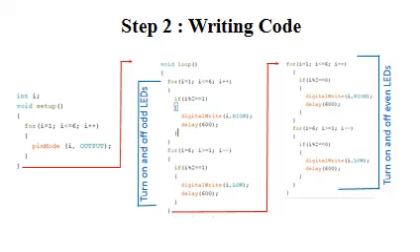After that, the third loop runs for the values from 1 to 6. If the value of I is even, then the LED will turn on by getting high voltage, and there is a delay of 600 milliseconds after each turning on. So this loop will turn on second, fourth and sixth LED sequentially.